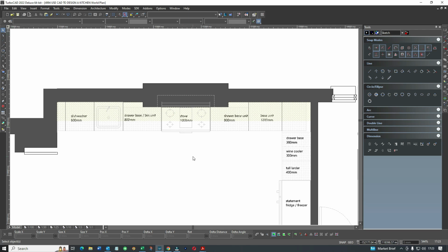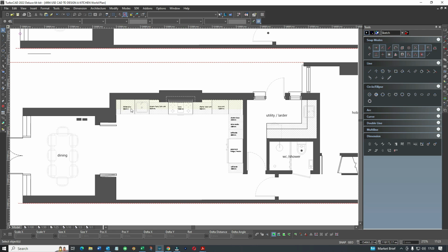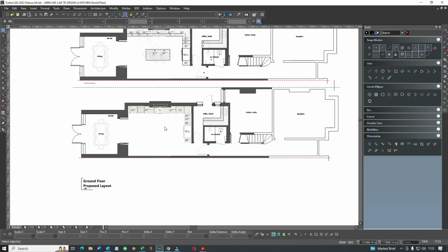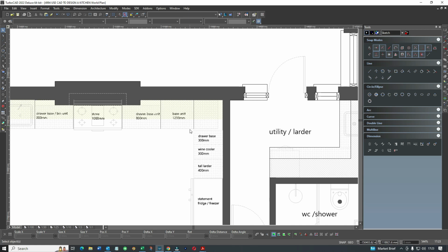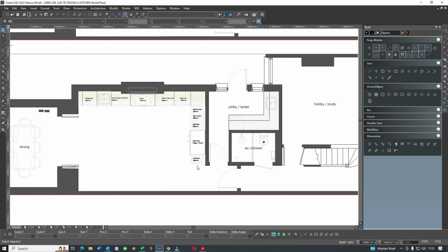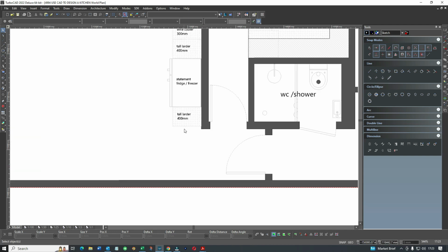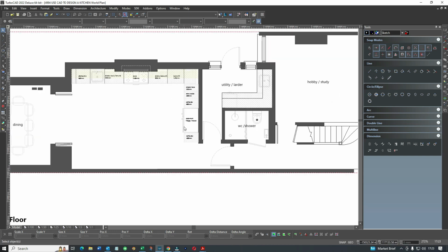Okay, kitchen, hopefully you have the basic bones for getting a kitchen plan going, starting in the corner, working left, keeping an eye out for the door handles, etc. And don't ever go the whole way to the end, you want to be kicking in a little. Fridge freezers, big appliances like stoves and so on, if they're freestanding, always allow maybe 10 mil on either side just to get them in. Worst thing you can do is have it perfect, because if you've got a 1000 mil opening to put in a 1000 mil appliance, you're just going to make a lot of problems for the installers. You need a little bit of tolerance.